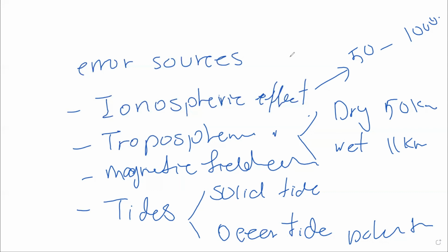So now I write this mathematical equation in a more complete form. SSH equals the satellite geodetic height plus its random errors, or the error of the orbits, which is also there, plus the altimetry measurement. And we know the altimetry measurement has its own limitations, random errors or other things regarding the sensor and also the transmitter.